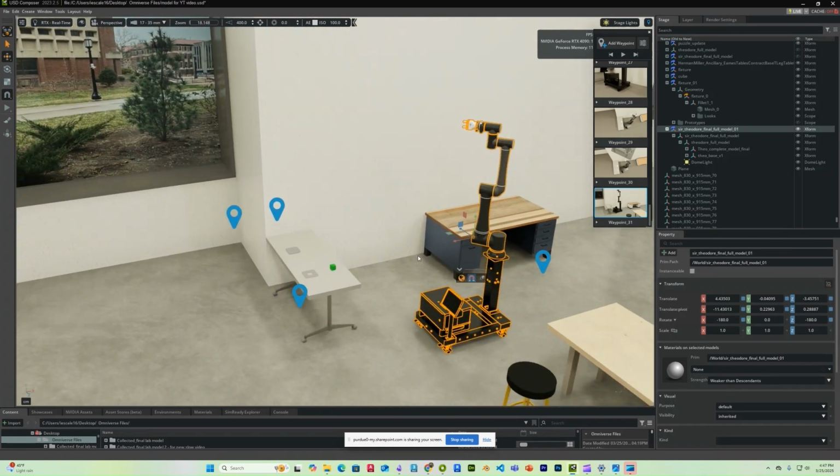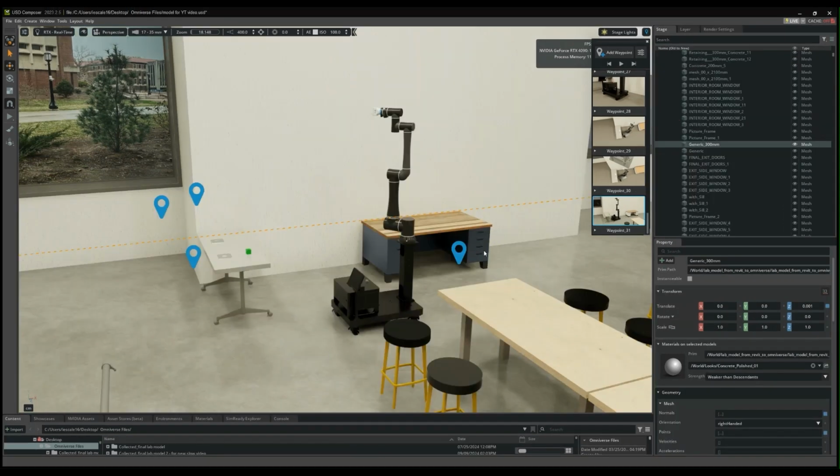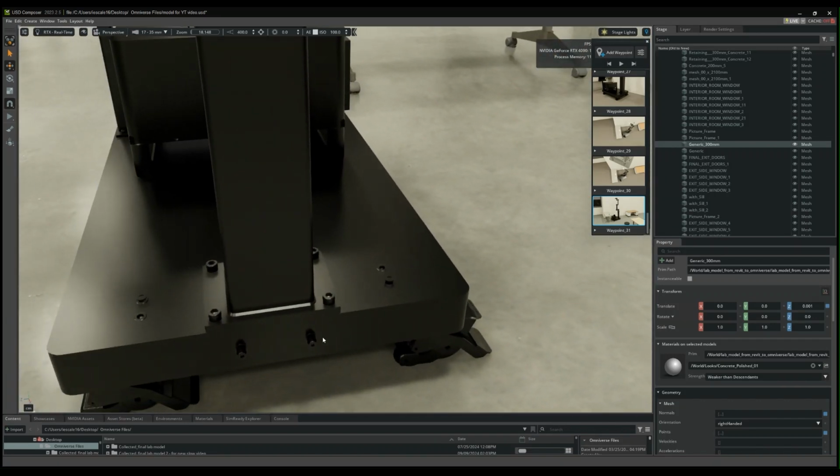Because at the moment, the entire model has a pivot point in the center, but we discussed how we are going to have the pivot point of the model on the right hand side corner of the base. So we're going to work towards making that happen. I'm going to now zoom into this area to position my pivot where I want it to be. So yeah, we discussed that we want the pivot point over here because this is a reference point that we use to measure the distances from the walls, right?